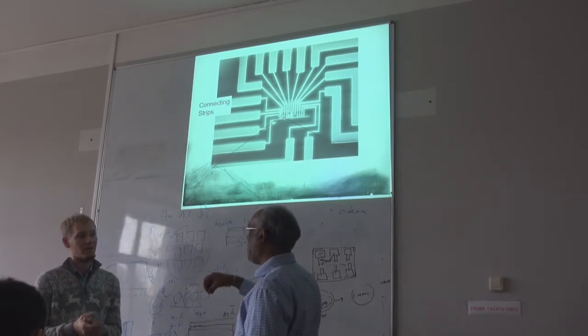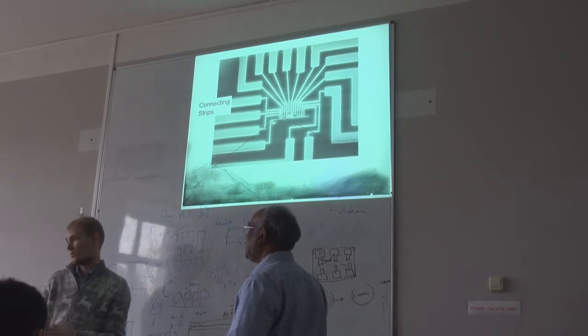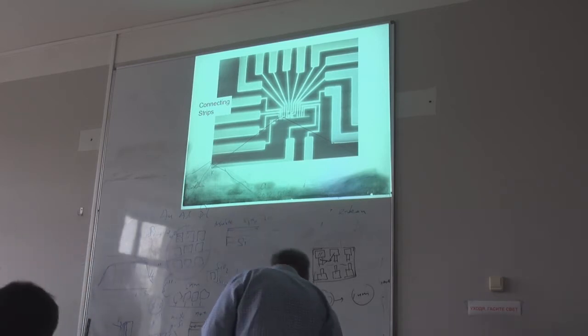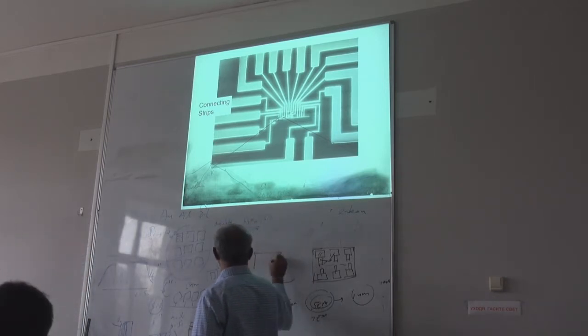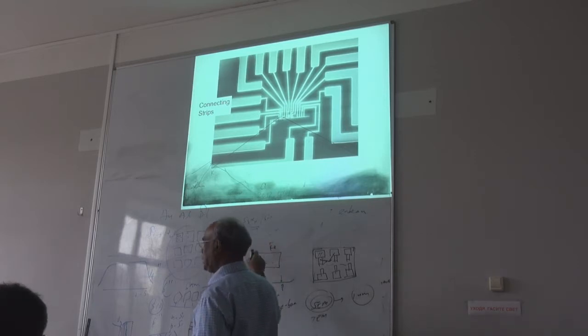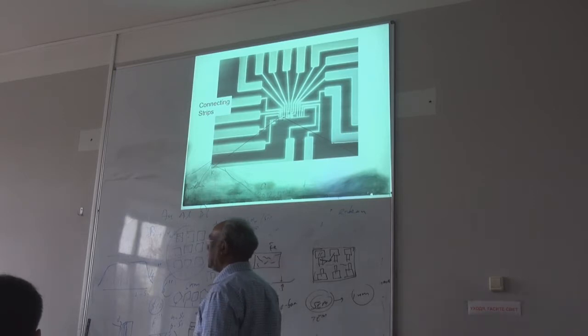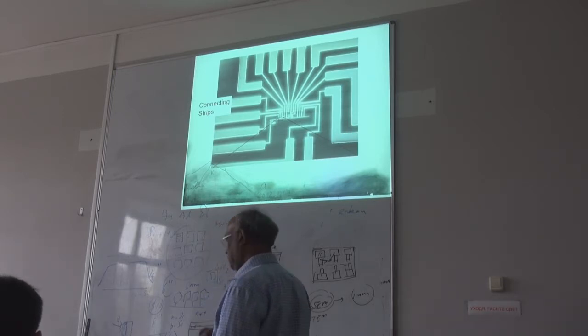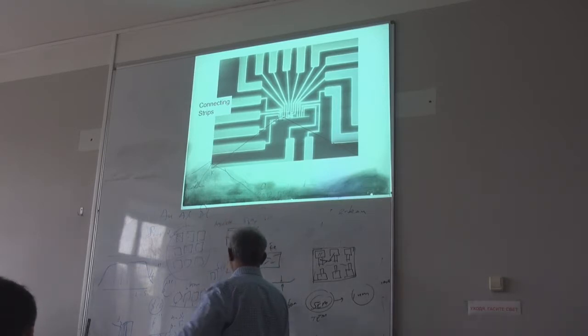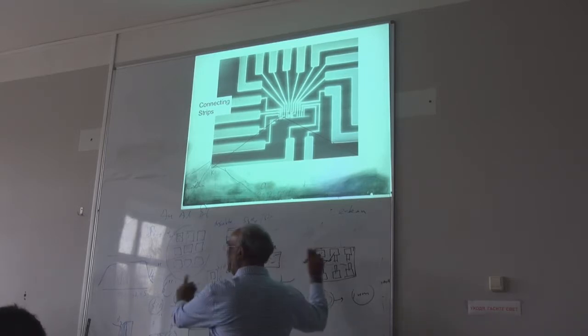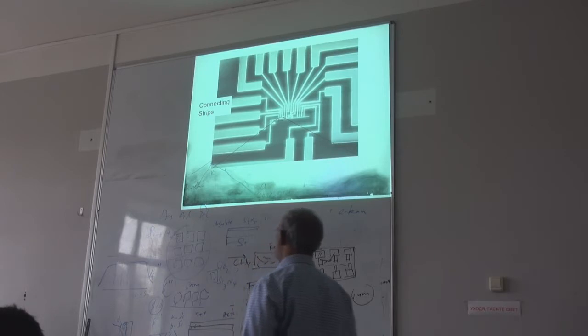Basically we put iron nanoparticles on the substrate, then put methane gas at high temperature, and they grow. CVD growth, like in yesterday's lecture. But we don't need a lot of nanotubes. That's the problem. If you have it like this, that's not good. We need very individual nanotubes.